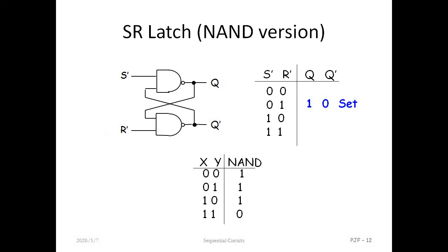When you see the previous state 0 1, Q is always 1, and that stored element comes to 1 1 1 1. So Q becomes 1. That 1 comes to the second NAND gate, that is 1 1 becomes 0. Here the output is 0. That 0 goes to the first NAND gate, that is 1 0 gives 1. So this condition is called a memory element, because we obtain output 1. It is also called a hold condition.